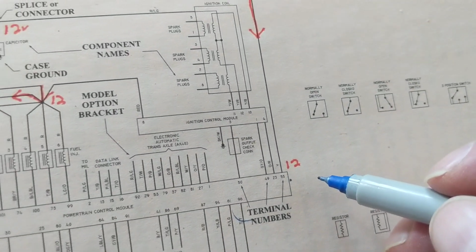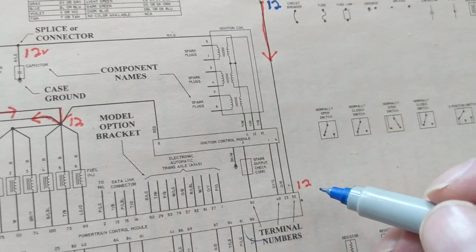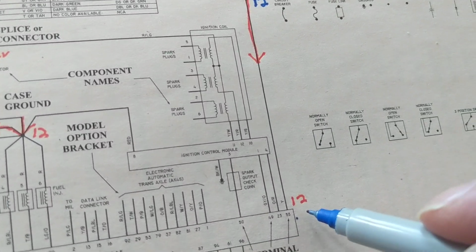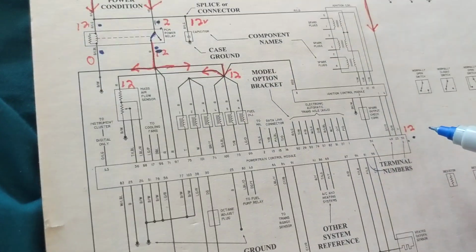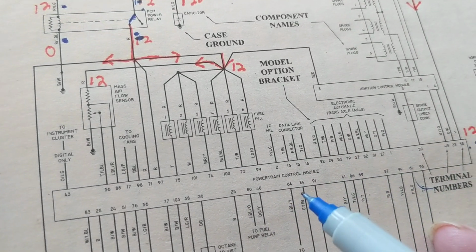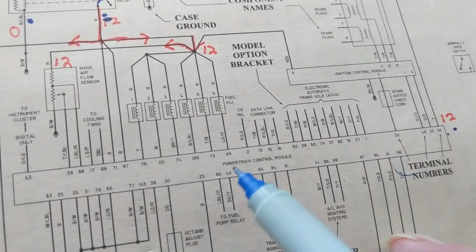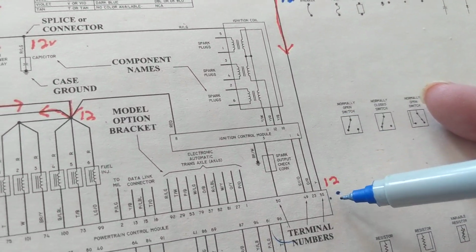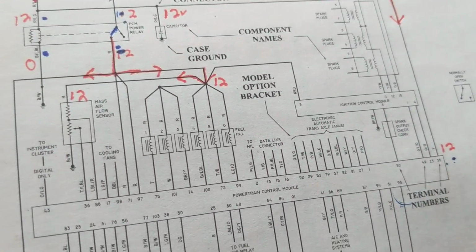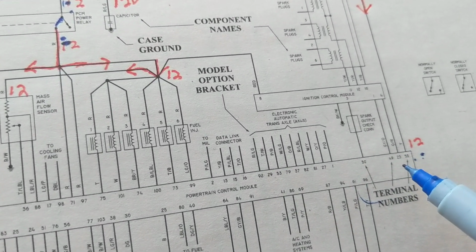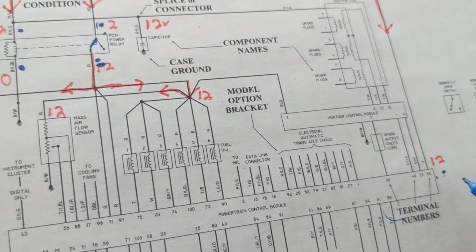So what's the main feed line? The main feed line is pin 55, if I ask you. Make sure that this gets 12 volts. Why do we need 12 volts? Because remember, this gives grounds. This has to be activated. For this to be activated to give ground to the fuel injectors, he has to get his main feed of 12 volts first. Now the question is, is there only one line of 12 volts? Or can there be many? The answer is there can be many.